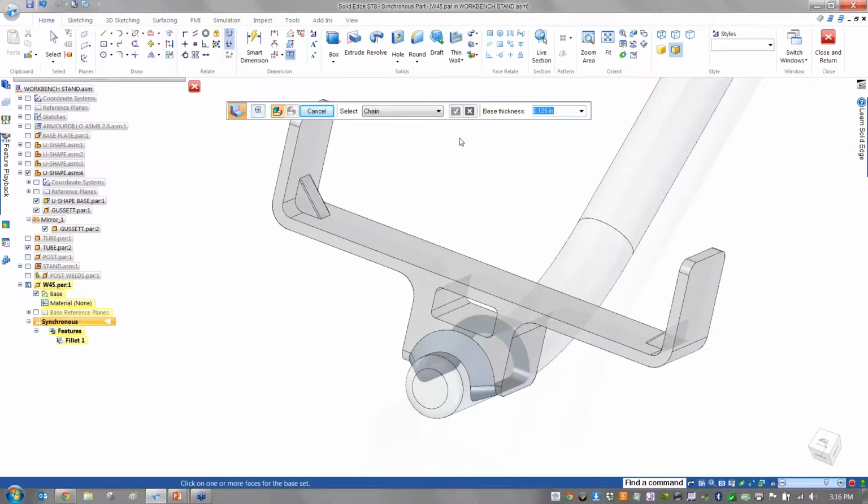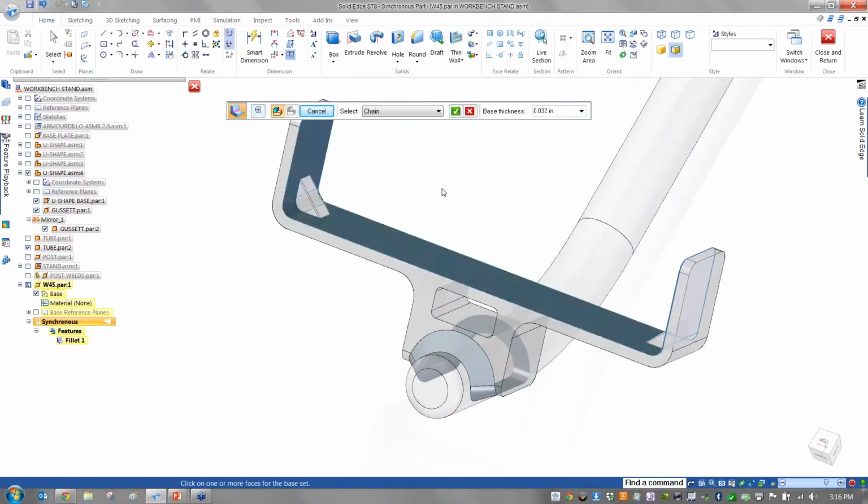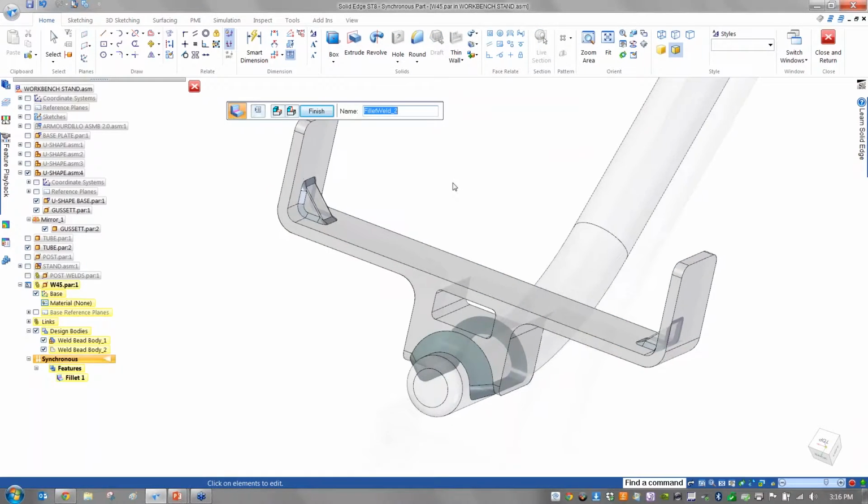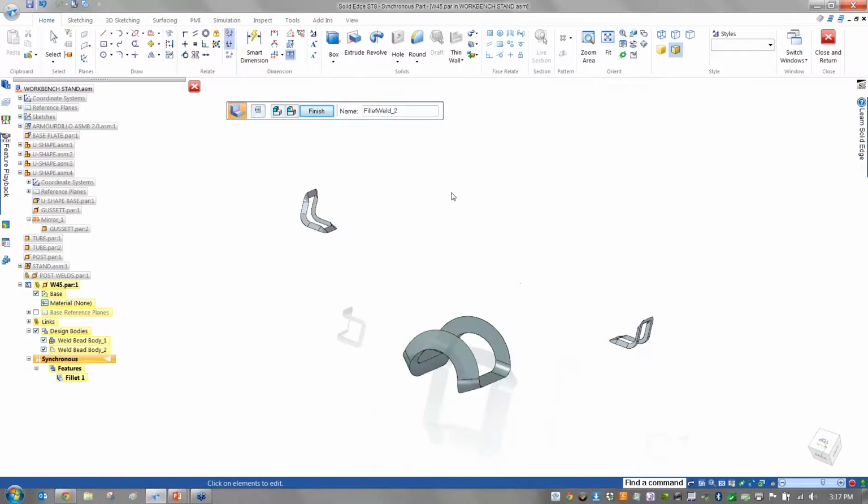So let's do that again, and this time let's just repeat it and set it up here just like we would with the Smart Step ribbon bar with any offset, any copy move so far. You know, just look at this, and I'll set it right up here, and I'll say 1/32 of an inch between this surface and this in the same selection. Here are my 2 little gusset pieces, and as I do, we'll just have Solid Edge put our bead all the way around there.